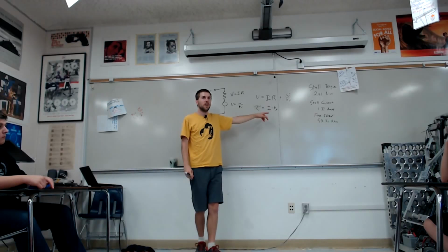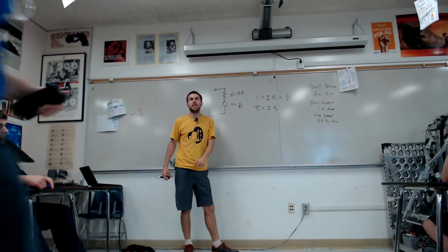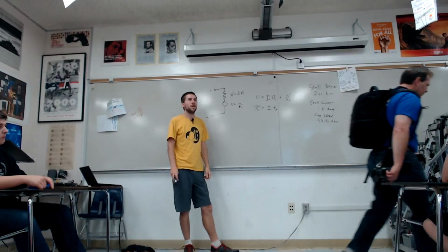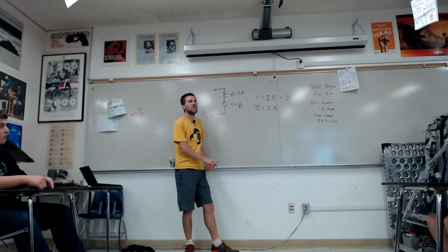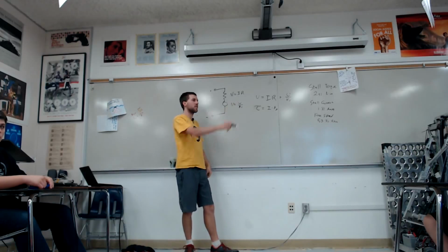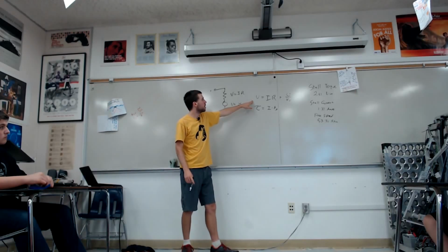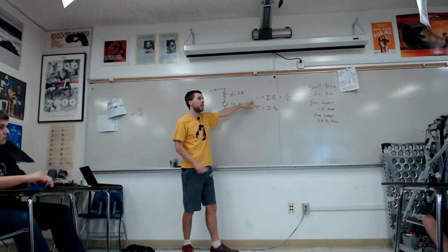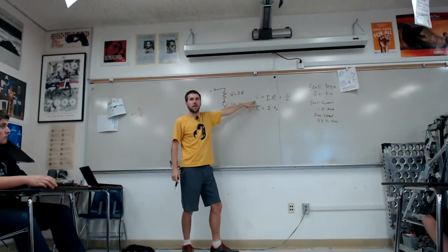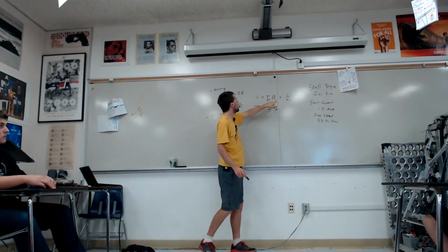From here, we can actually calculate R, KV, and KT. Does anyone see how to get one of these constants? Yes? You can set your voltage all the way up and then have it stall to get just IR. Okay, so what does stall imply here? Your omega is 0. Okay, perfect. So if we're going to check at stall, this is going to be 0.